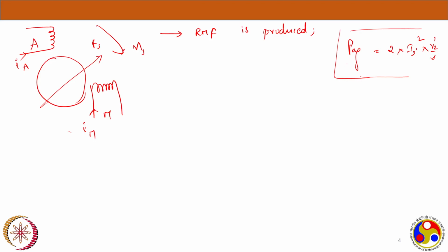So the idea is we take any unbalanced two-phase system, the current or voltage readings which we are sensing for the motor, and then we can show that any such system has a balanced positive sequence and also balanced negative sequence components.